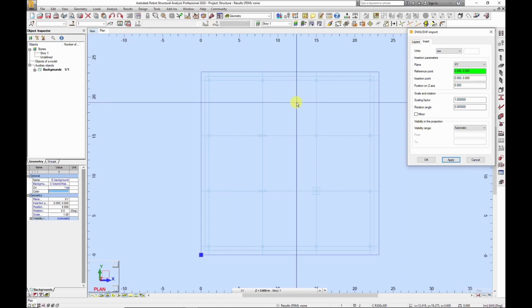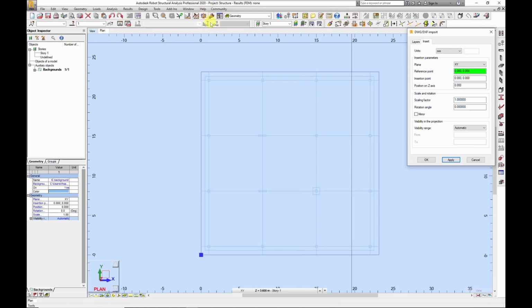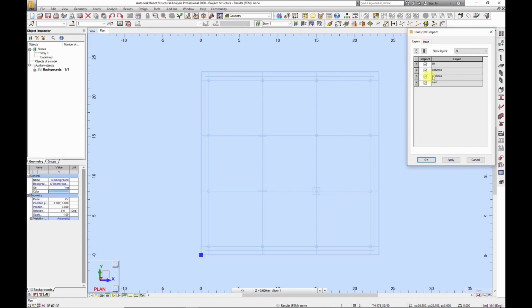It's in the AutoCAD tutorials that I pointed you to, but in the options here, if you choose the wrench option, you can look at the job preferences and the preferences in the software itself, and then set your units. I can go into layers, and these were the layers that we saw in the CAD model. It's up to me. I can choose to import them all or only a selection.